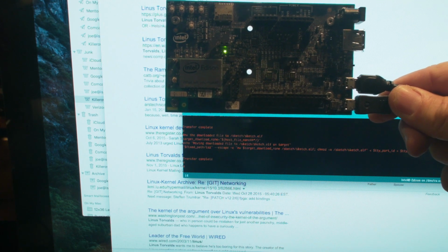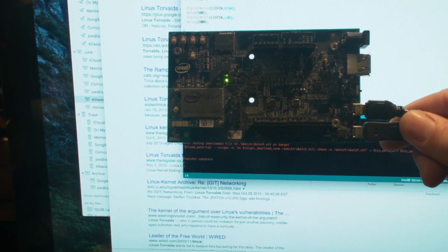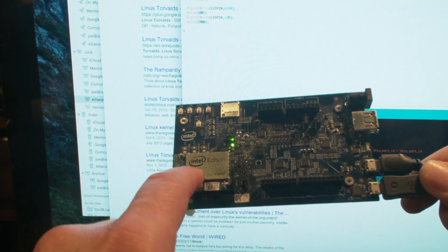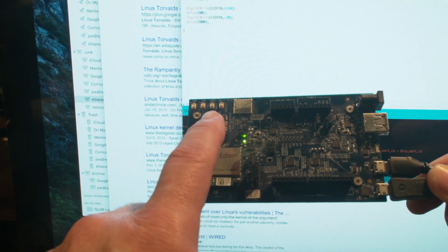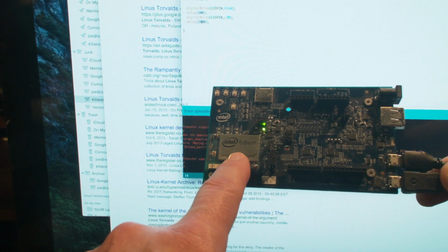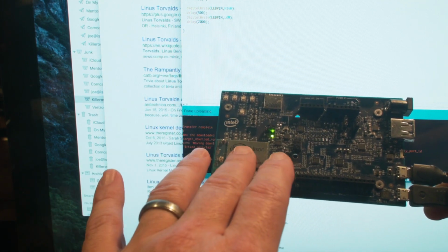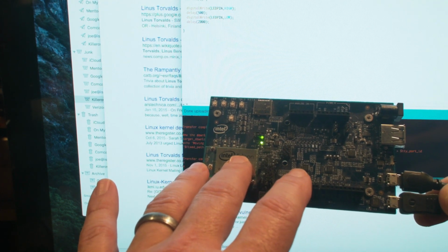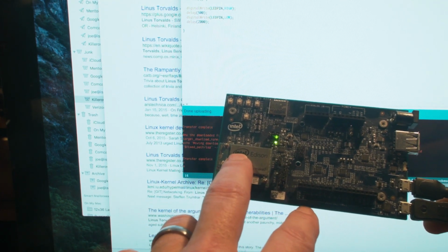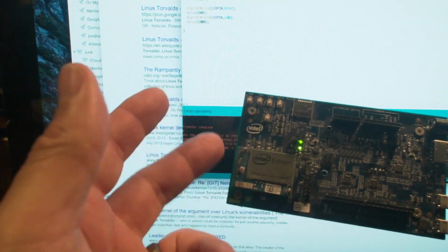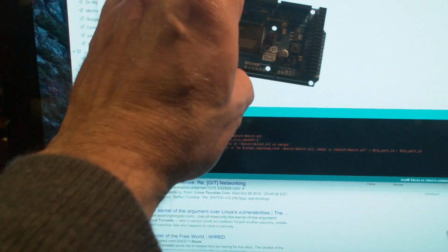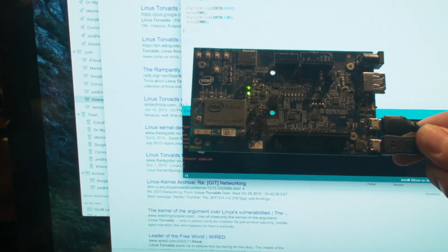All right, so you get the idea that I'm actually programming this thing like an Arduino. Again, this is a single board computer running Yocto Linux. So it is running Linux. But we've got a little program running in this that makes it look like an embedded controller, a microcontroller. And so when the Arduino software comes into it, it thinks that it's sitting in a regular old Arduino just like this, and it does everything the same way that it usually does, and all this hardware mimics this hardware over here.